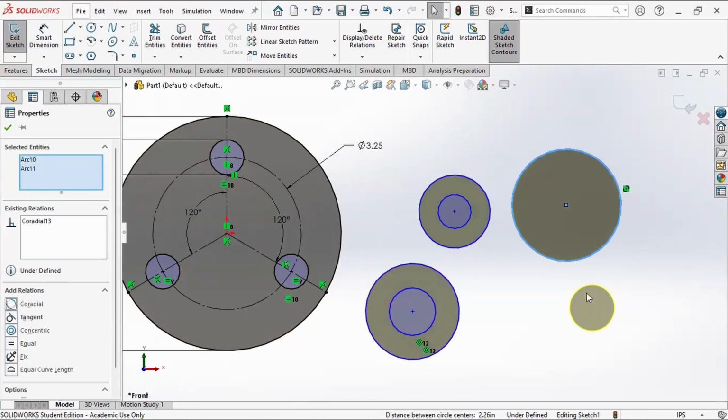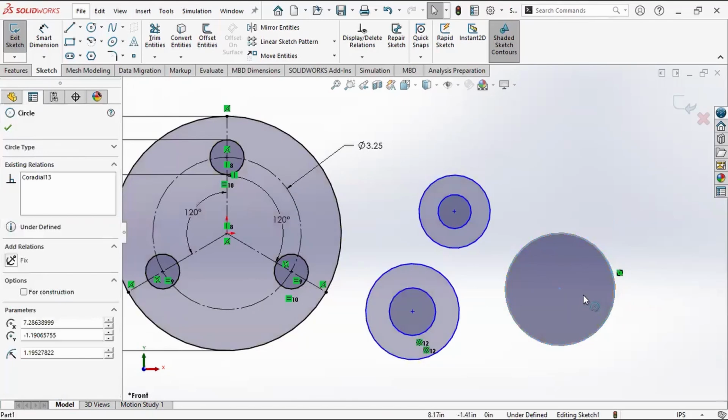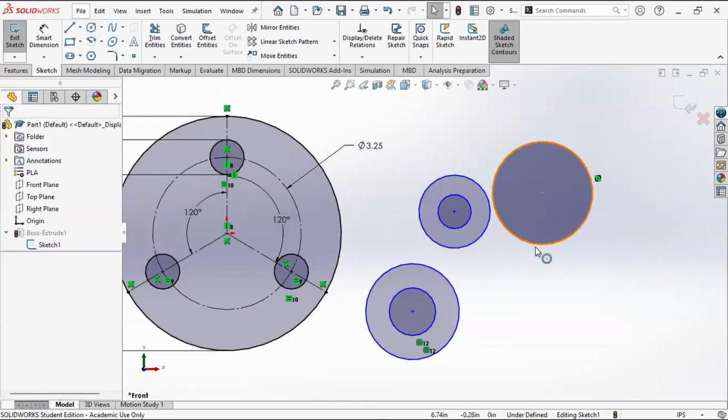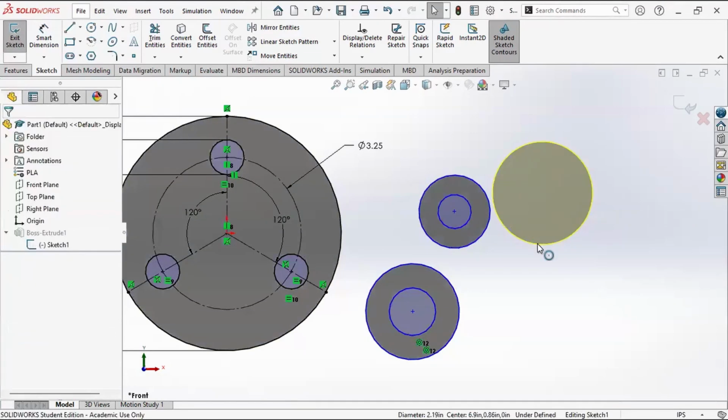notice the yellow is where the smaller circle was. It is now in the big circle. But because they have the same diameter, I no longer can even see 2 different circles because they're co-radial, right? They have the same diameter and the same center point. That is useful later on when we get into adding sketches on top of parts that already exist. Occasionally, we will want to use a co-radial constraint as sort of our definition point for building off of other features of the sketch.